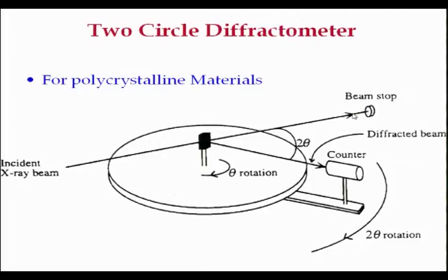So, it will start at 2 theta equal to 0 degrees or close to 0 degrees. Typically, we start from 5 degrees in wide angle X-ray diffraction. It will start at lower angles and go up to nearly 150 degrees. On the way it will collect all the diffracting peaks. So, this is the modern diffractometer. You can also rotate the sample to maximize the probability again, but you do not need to do that for polycrystalline material unless you have texture or something like that.